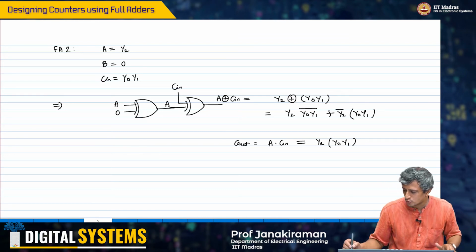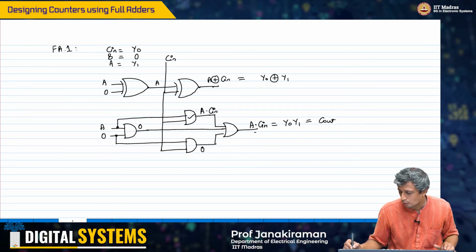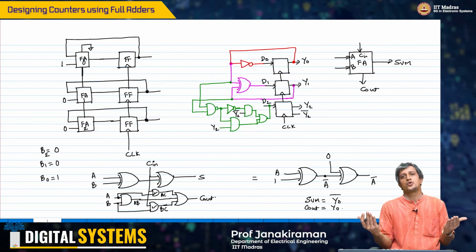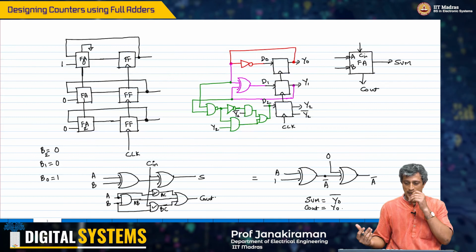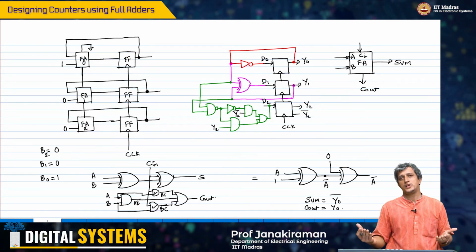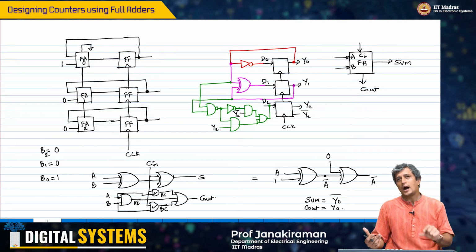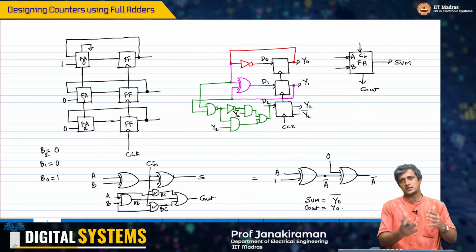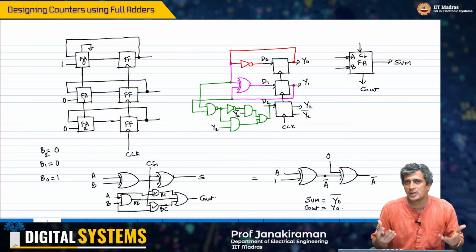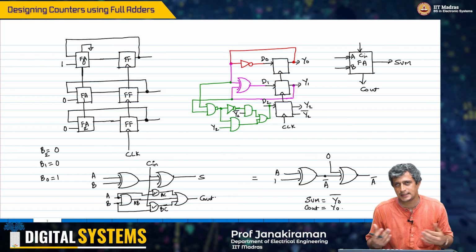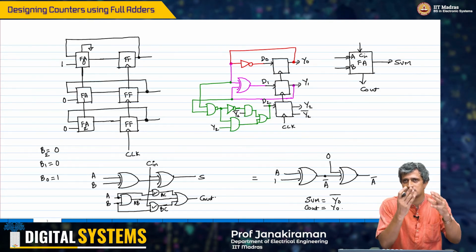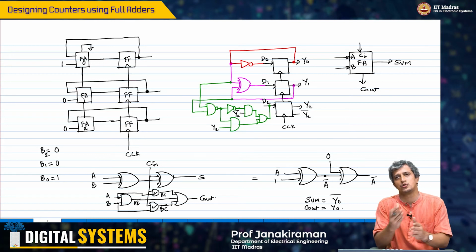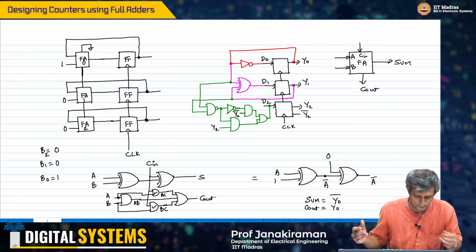So I wanted to highlight the importance of making sure that two designs are equivalent. And they indeed will come out to be so if you consider the hard-coded values that we have put into this full adder. Sometimes even a multiplier we might choose to do something like that. You must know how to consider the hard-coded inputs and reduce the logic diagram accordingly, right?